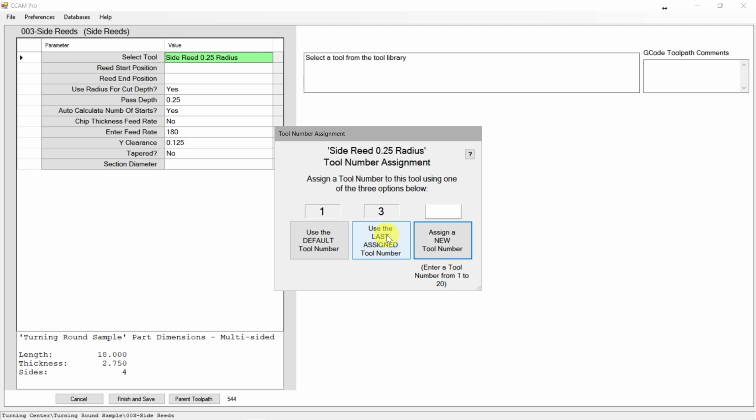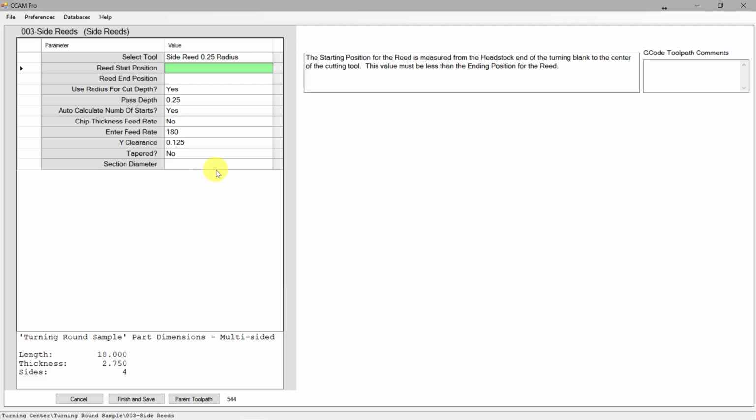Instead of being tool number 3 like the others, where the first 2 cutters are the surfacing and classic spiral, and then this would normally be tool 3, I'm actually going to assign this to the tool numbers that represent a manual tool change in the Delta controllers right now. And that will be tool 8, 9, 10, 11, and 12. So I'm just going to choose the first one as a manual tool change, tool 8. When it actually asks us to put the tool in, it will do so as a manual tool change instead of automatically picking up the cutters if you have that capability with your machine. So just a precaution, make sure you're assigning this specific cutter, because of how long it is, to the right tool number.